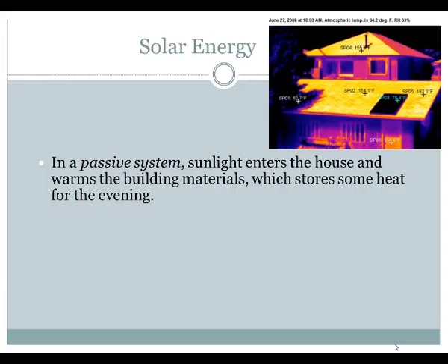This picture right here shows a thermal image of a house, and so it says that the atmospheric temperature for that day was 84.2 degrees, but you'll notice different parts of the house have temperatures that are much greater. So right here in the shade where the tree's protecting the house, we have 82.7 degrees. Over here where the sun is hitting the shingles, we got 154.1 or 162.3 degrees Fahrenheit. So many building materials, as they absorb solar energy, are going to increase in temperature.